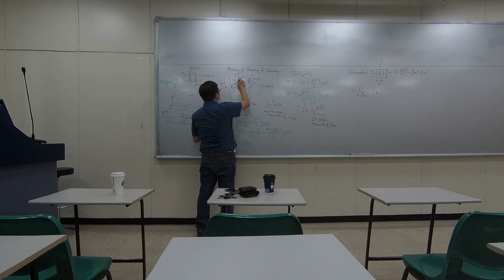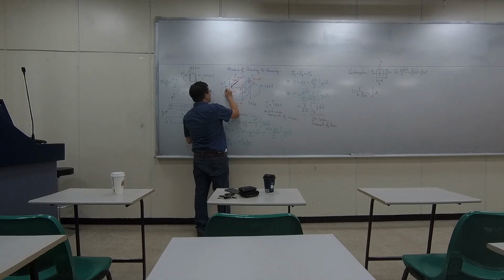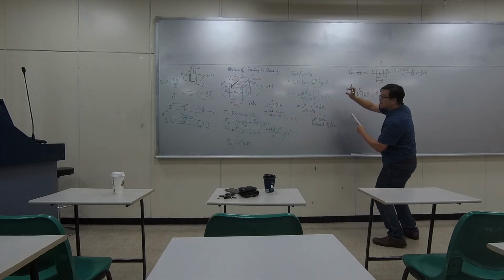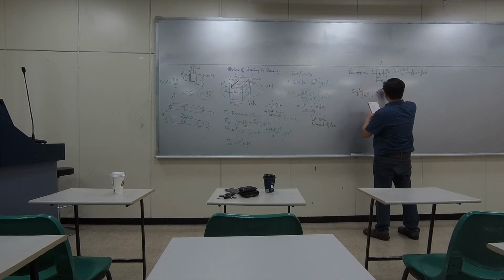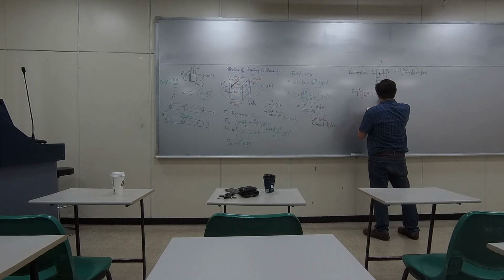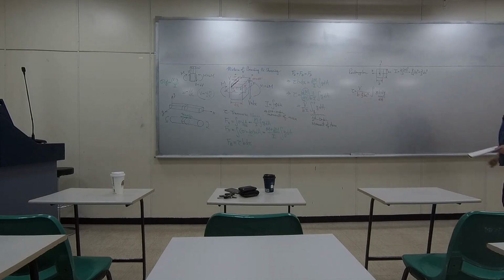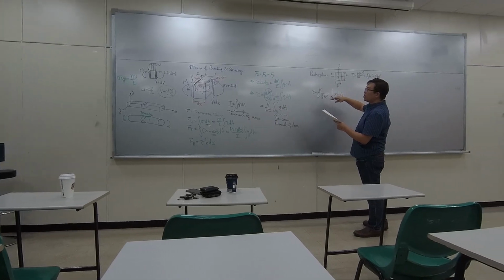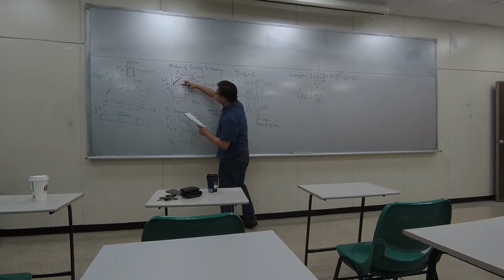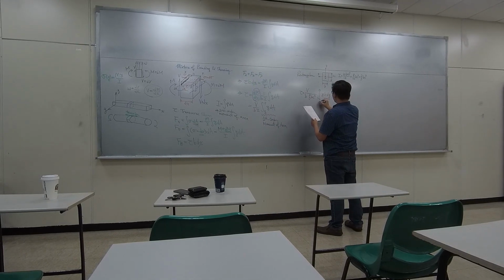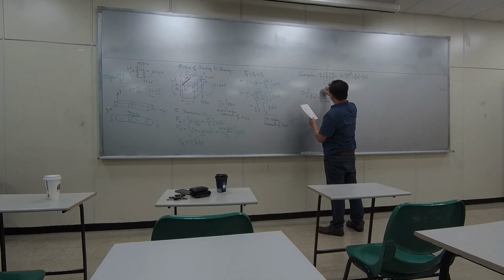Sorry, because we are summing everything up. So this is one slice, this is dA. The height is dy, and the width is b. So here is b dy. This was dA, the exact one that I drew on the left, and then we are taking integrals. So we are studying from this position to the very top. That position is actually y1, and the very top is c.